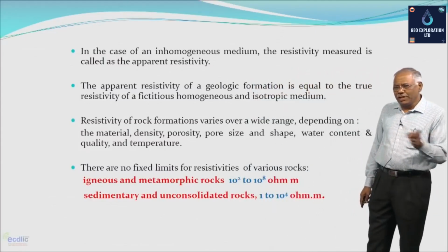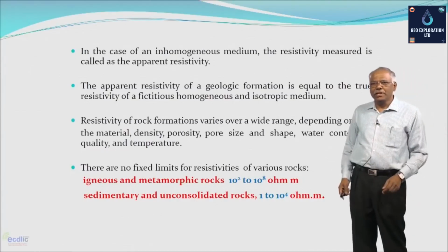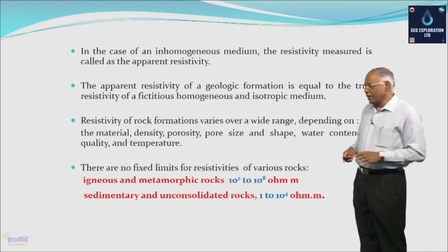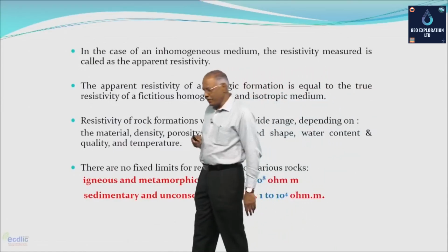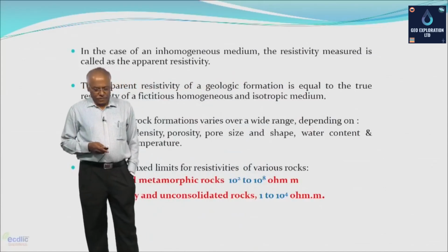Plus, if you look at the other types of rocks, which are soft rocks or sedimentary unconsolidated rocks, they have a range from 1 to 10 to the power 4 ohm meters. And therefore, from these two ranges, one can say that there are no fixed values for the resistivity of different types of rocks.